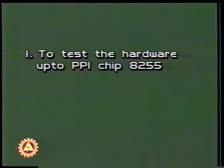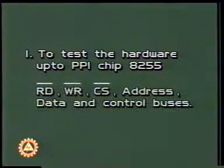If there are any malfunctions, we analyze signals, read bar, write bar, chip select, address, data and control buses and rectify the faults.